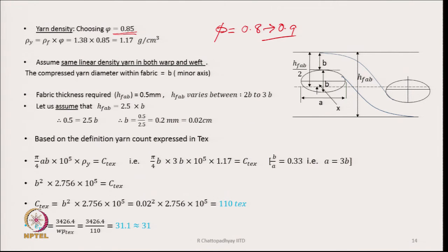You have to remember, this is not outside the fabric. Within the fabric, the yarns are locked in positions and there are pressures, therefore, they are highly compact. So, packing coefficient is very high. These are filament yarns. For spun yarns, packing coefficient cannot be 0.8, it will be much less.